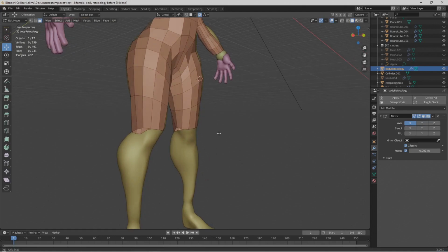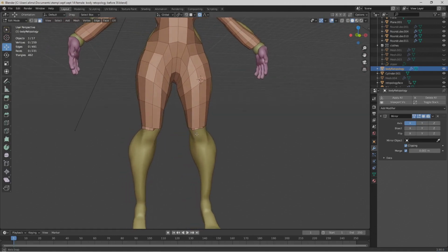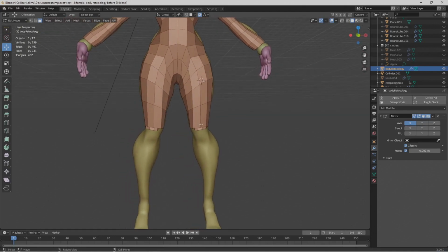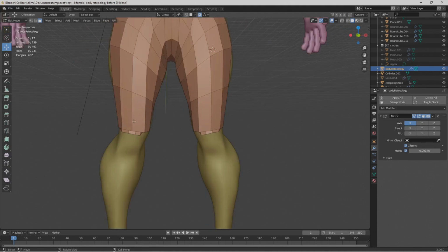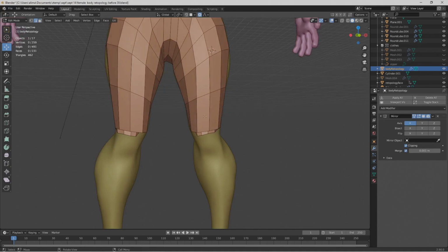Okay, what I want to do here is reduce the geometry coming down. See these two faces right here? These are very important. I'm going to roll the mouse wheel to zoom in. I'm going to look at these two faces, right? I'm going to go to the edge here. And then I'm going to hold Control, then right click. So here's the edge. Now I want this edge to run this way. Currently the edge is running down.